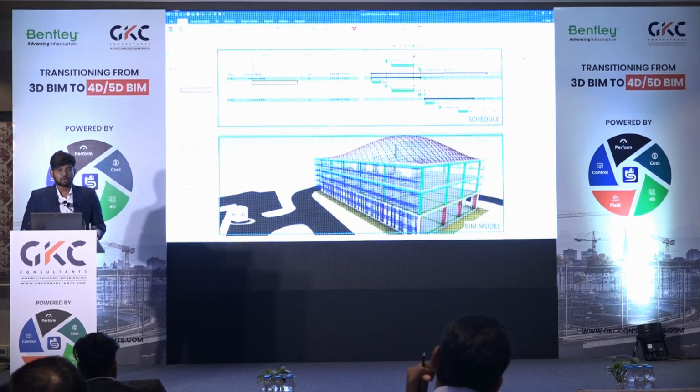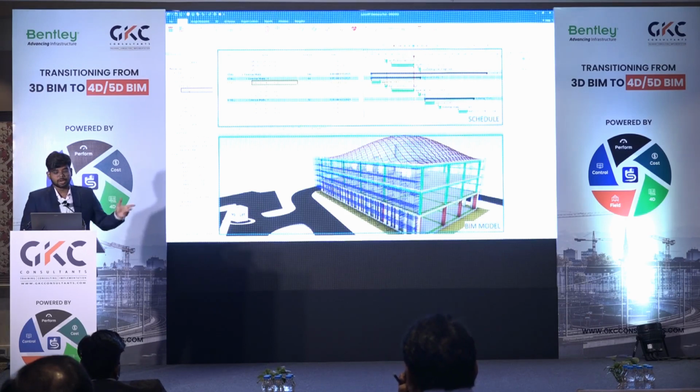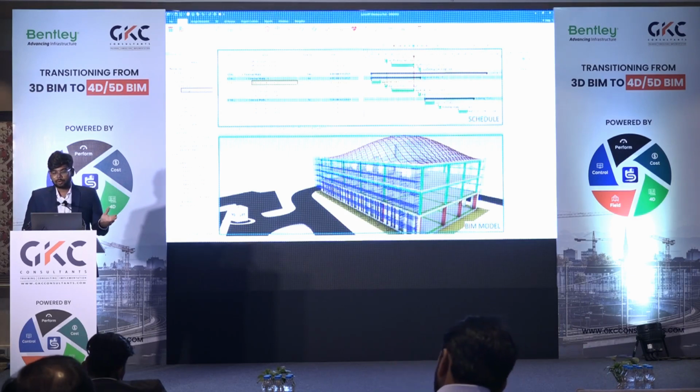And this is exactly where we start the 4D modeling or the 4D planning. Because as a planner, or as a person who is going to decide how the construction is going to take place, you start tinkering and tweaking with this schedule, and you start seeing what is the best one. Now, Synchro is a full-blown CPM engine, so whatever features you have in a conventional planning tool, those options are all there, like the critical path method based on forward or backward or based on the least float path. All of them can be done up here, and you can start creating your 4D model.